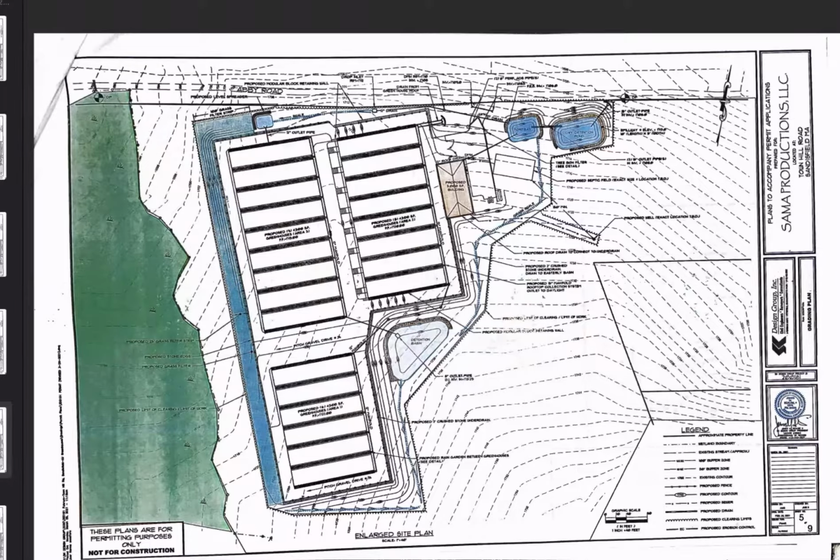I'm sorry, I'm on sheet 5. And I've carefully collected all the stormwater off all the roofs into swales and drainage catchments between each greenhouse. So there's a complete control of stormwater on the site. There'll be no concentration or diversion of stormwater, which is against the building code, and also against the stormwater management standards. So there's a very detailed report and analysis.